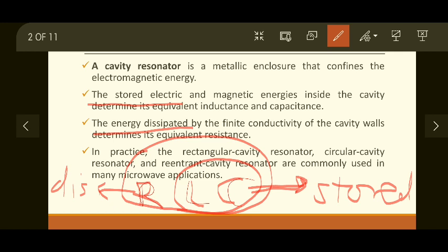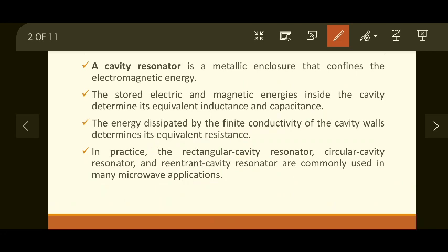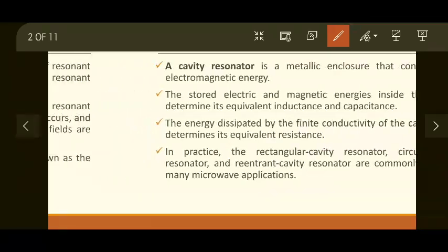You have to go for different solutions for creating resonators at microwave frequency. You can use transmission lines, we can use cavities, that is waveguides, and different other devices for constructing resonators. So first let's look at the rectangular cavity resonator,